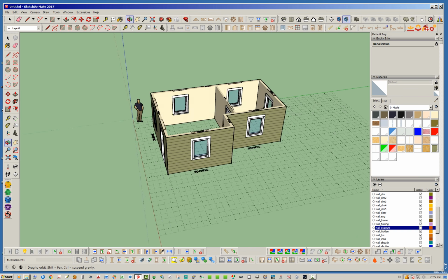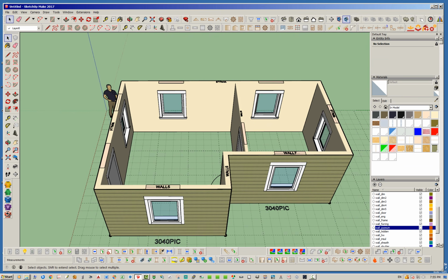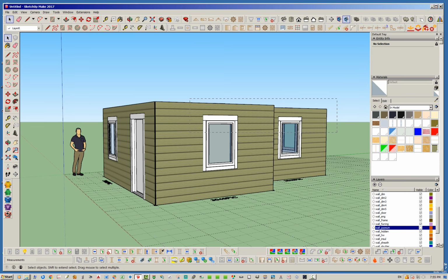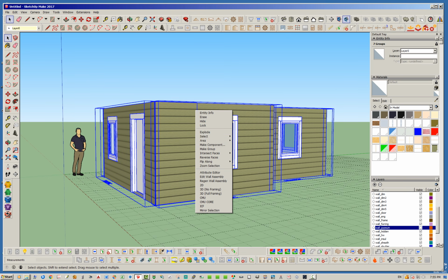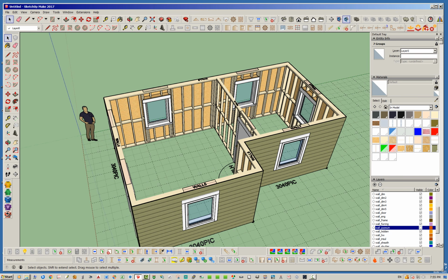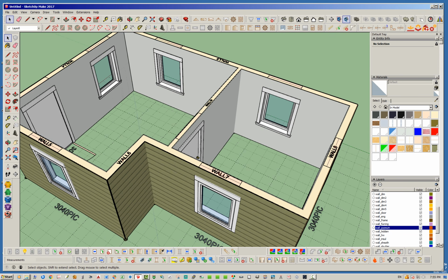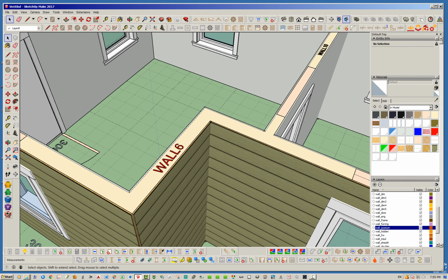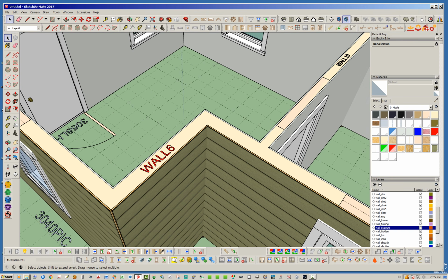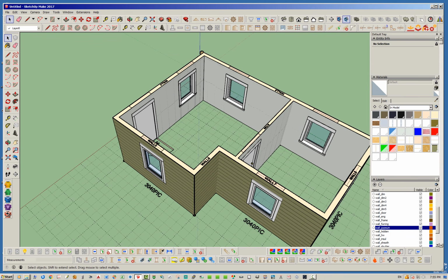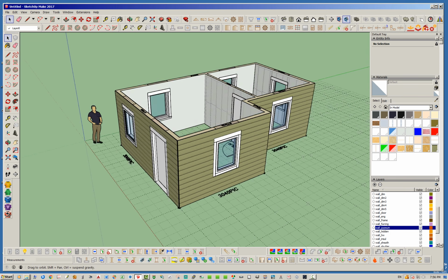And by the way, this hide wall line option also works if you turn all the 3D framing on. So let's go ahead and turn that 3D framing on. Go ahead and regen that all, and you can see that it's now all framed out, but let's put the gypsum back on just so we have that right next to it. Okay, but you see all those lines are not shown, right? So it looks like one big monolithic piece that forms the framing of this structure. So anyways, a couple things on that. Just wanted to re-clarify that and show you guys that.